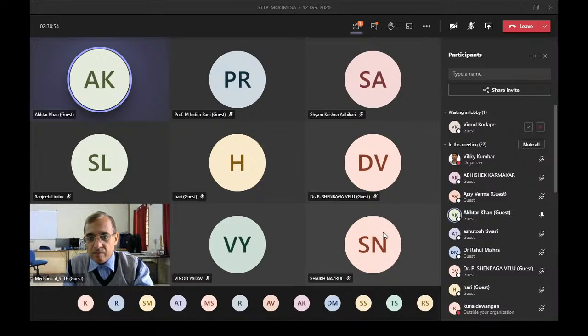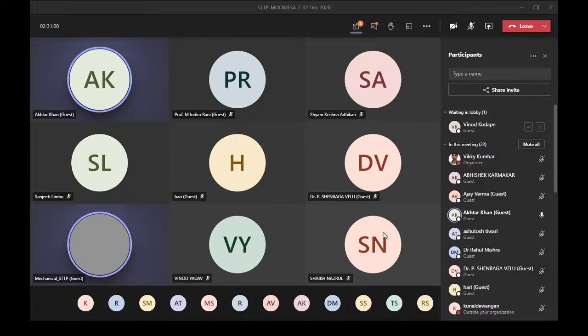In Minitab itself, there is a menu called Graph. If you select that, at the bottom the response surface is mentioned there, 3D response as well as contour plot. You need to select any one, and you have to select all the axis values, x, y, and z axis. It will give you that particular graph, and you can interpret it. This Pareto graph representation, I don't know if it is a part of RSM. But RSM includes response surface and contour plots.